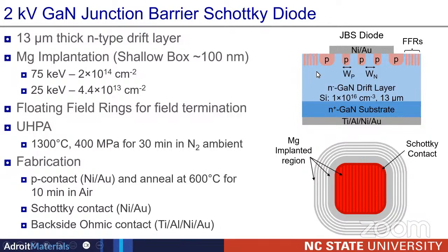If you want to block more voltage, you need more material. You can then design the thickness and doping of the material based on the required breakdown voltage. There are already theoretical equations that we can use, and we can also simulate, as I was showing in one of the simulation results.